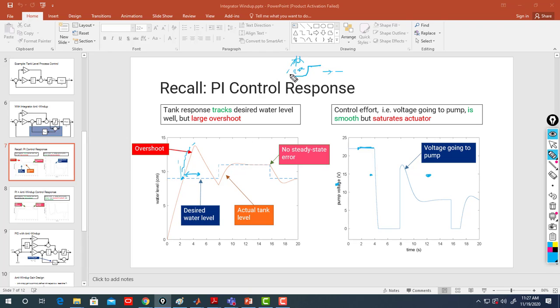But you have already accumulated too much energy. So the command signal is going down, but you are still saturating, because you are still above the saturation limit. You are going down, but you're still above, so that's why you are in here, and that's why you are overshooting. In this time from here to here, from 2 to 4, you are overshooting. Then later we start to decrease.